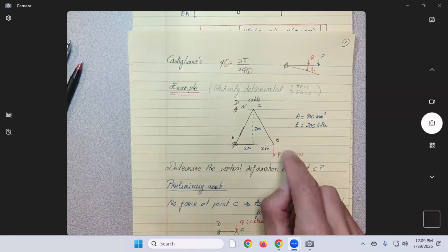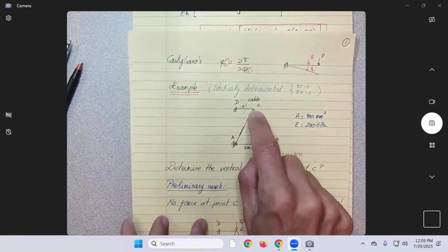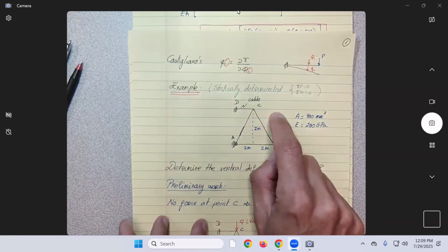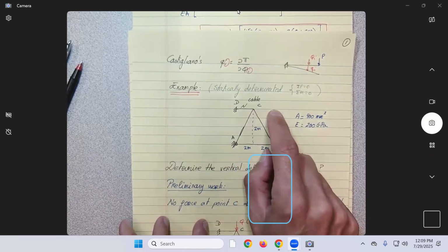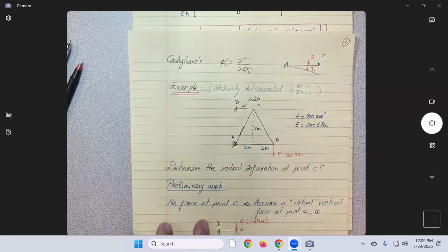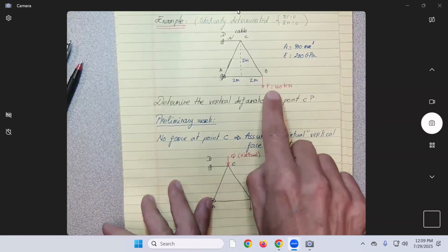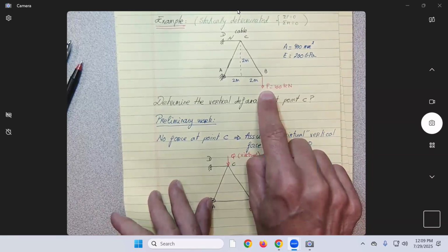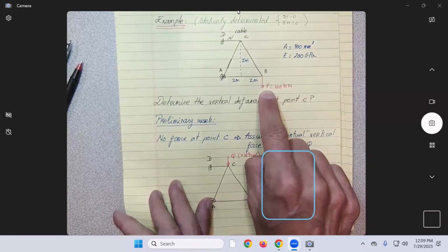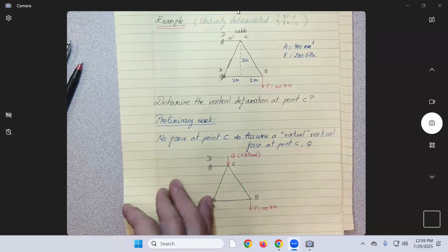Yeah. So imagine here we just calculated the vertical deformation. What happens if you needed to calculate the horizontal deformation? You will have to redo the whole work with the horizontal force. But if we had solved the same problem, and the question was to determine the vertical deformation at point B, did you need to add a virtual force? No, because you already have the force F, no? Okay, so we could keep the force F over there.